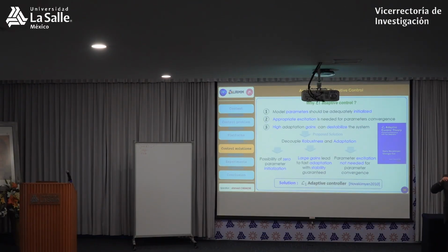To control the airplane, you need the dynamics. At that time, they're using the PID controller, and they use a model. And for the PID, you need a linear model. So you have the non-linear model, you linearize, you obtain the linear model, you design your PID, and then you use it in real time.